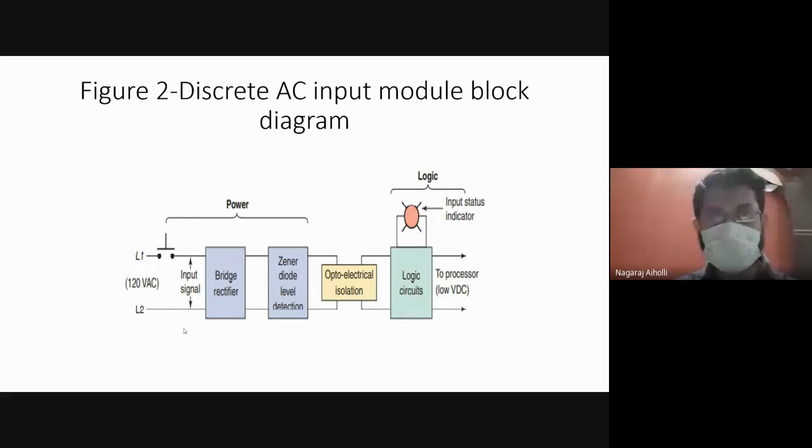You are right. So there are basically two types of rectifiers. One is the half wave rectifier, another one is the full wave rectifier. When you apply a sine wave input to the half wave rectifier circuit, the output you get is only one portion, either positive pulses or negative pulses, based on the orientation of the diode.